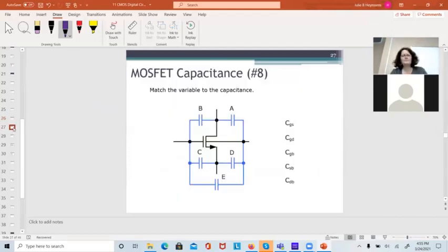Okay, good. Now, inside these MOSFETs, there's capacitors. If you think about the gate itself, the gate is a metal, then there's an oxide and a semiconductor. That's called a MOS capacitor. So there's other capacitors in there from other things that we'll talk about in more detail in 380. But this is pretty much most of the basic capacitors that people model and put into the Multisim model of the transistor and put into the Mentor Graphics and the Cadence model of the transistor. They all have names.